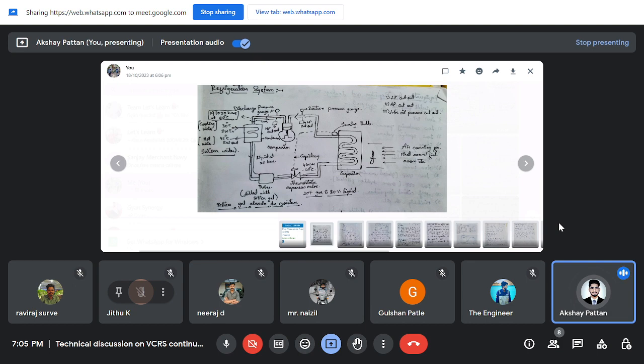So at that time, when the temperature is achieved, there is a low pressure in the evaporator coil and a low pressure in the flow of refrigerant. That's why it senses and cuts out the compressor. The compressor stops when it achieves the desired temperature. That's why the low pressure cutout is used, and it is fixed at the suction side of the compressor.